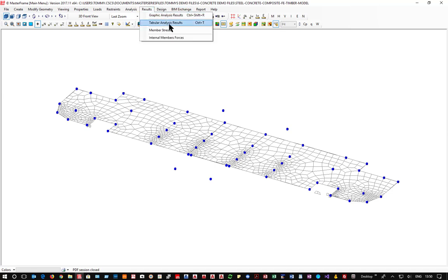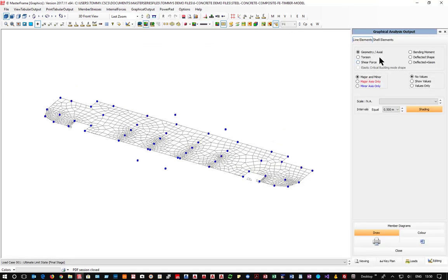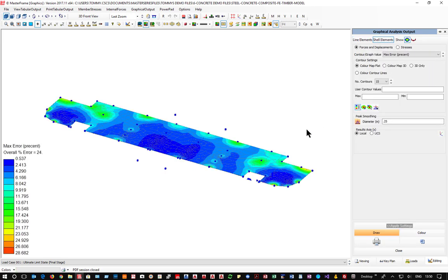And now results, graphical results, elements. And there we see we're getting a lot more blue, very little green. There's a wee bit more green, so maybe we should go for each of these points and do that higher resolution of mesh. But there's very little, and those are acceptable around these nodes. Just from inspection, but around here, yes, I would probably prefer to see these again also meshed to the finer mesh. So we've done our checking of errors.